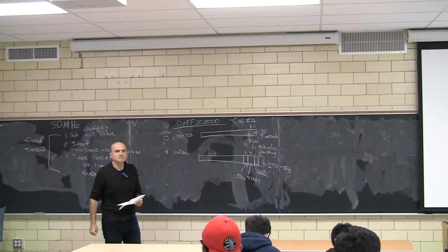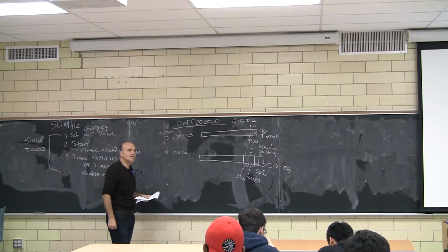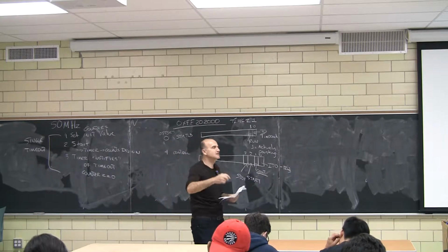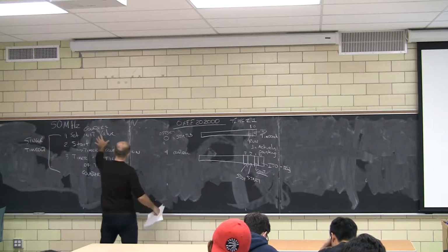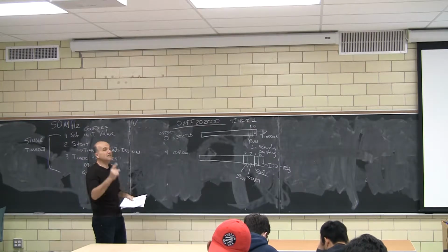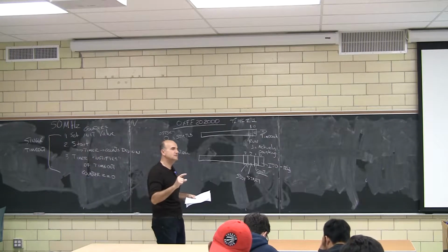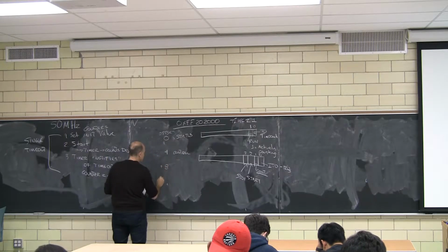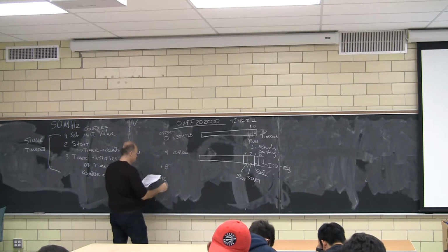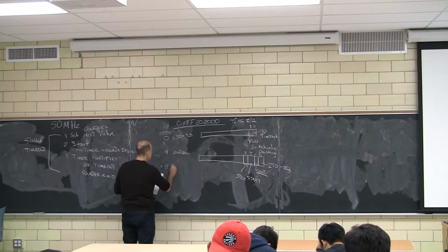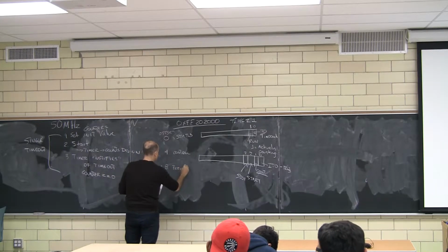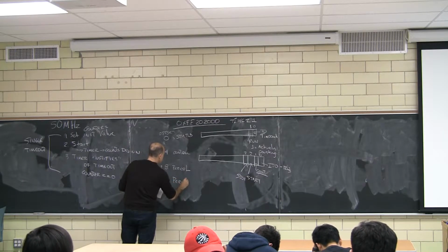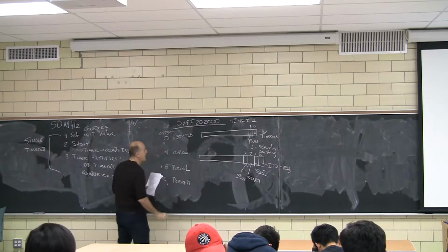So far, so good? Now, if you haven't guessed it, the last 2 registers are the ones we're going to be using to specify where we count from. What's the initial value? And these are 32-bit registers. However, they're funny the way we use them. So at distance plus 8 and distance plus 12, you have 2 registers. One is called period L for low, and the other one is called period high.